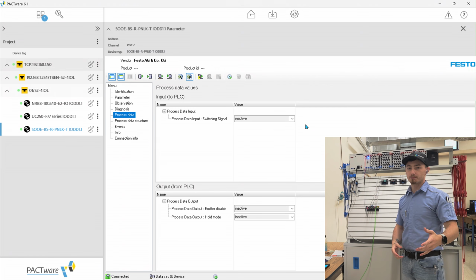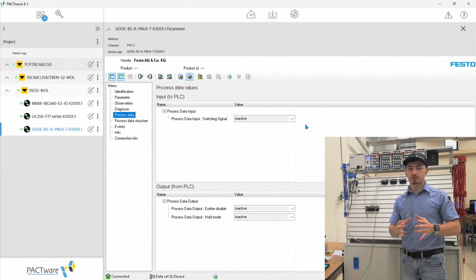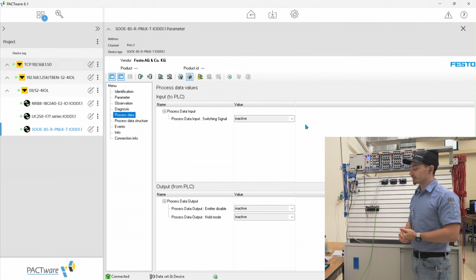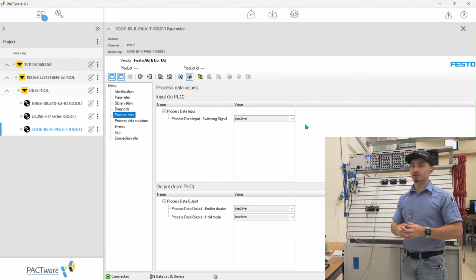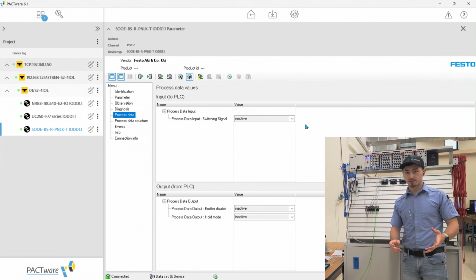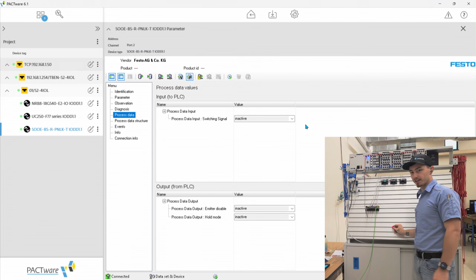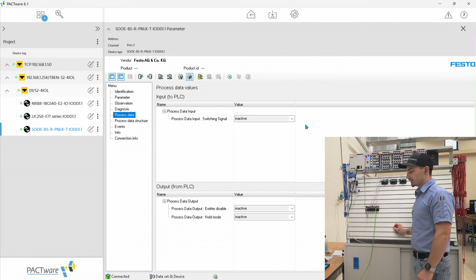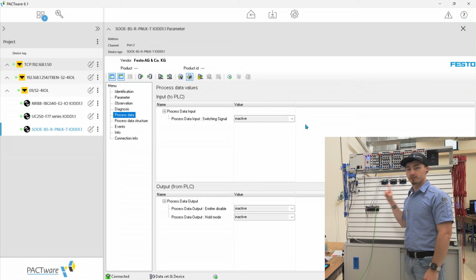Another type of light sensor is called a retroreflective sensor, and it's similar to the through beam, except there's not two actual electronic devices or sensors. So instead, you're going to have one sender, and then you're going to have a reflector that is somewhere on the other side of it, and it almost does the same thing as the diffused, except you have the reflector, and that shoots that light signal back to the sensor, and it receives it.